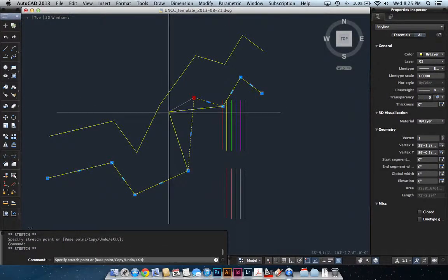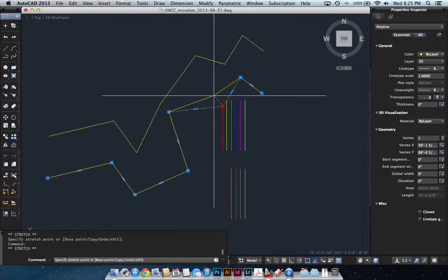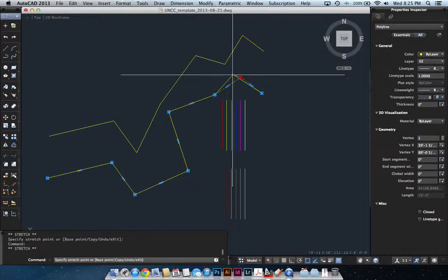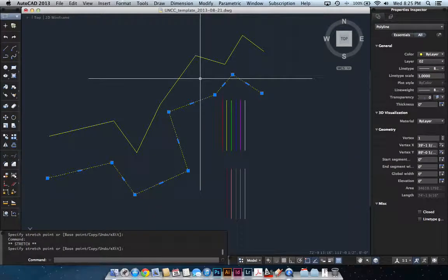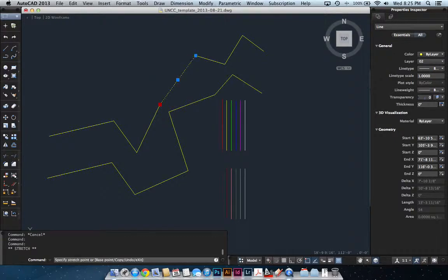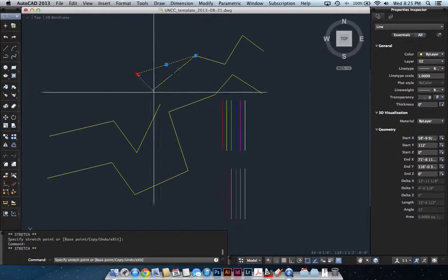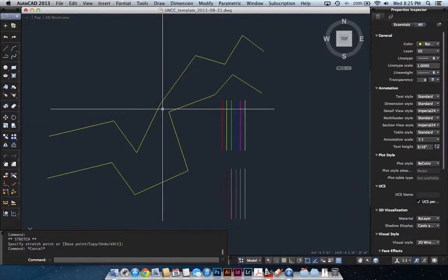Again, the blue grip by default is typically the activating of the vertices and nodes that you can grab hold of to snap to and distort to other things. Whereas if I grab this line and this line only and I move, notice it did not stretch that line with it. So that's the fundamental difference between a line and the polyline.